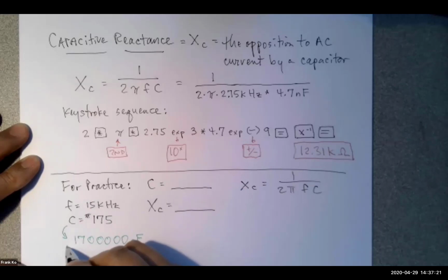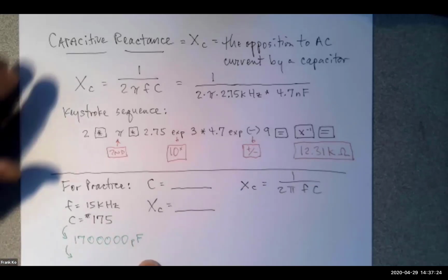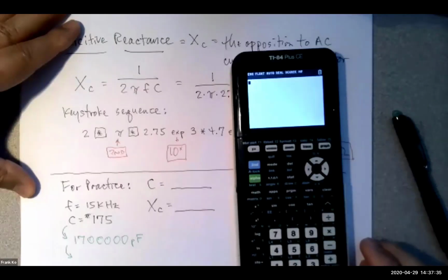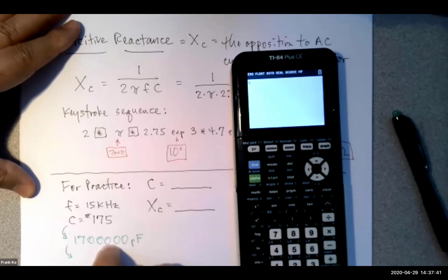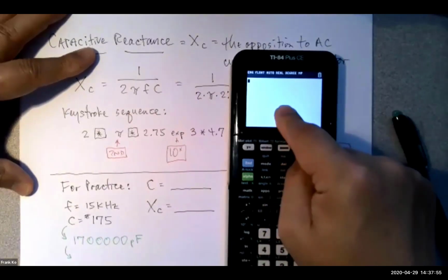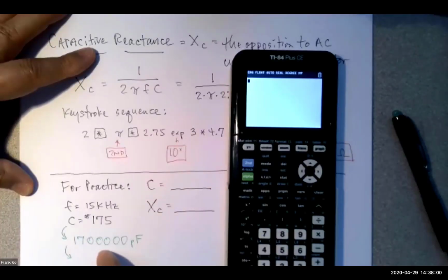What do I do with this information in the decoding process now? The question goes to Andrew. What do I do now? You want to take that over and put it into nanofarads? Well, is it always going to be in nanofarads? We need to find out. What do I need to do with this to determine what this value is going to be? Because it's not always going to be in nanofarads. You have to times it by 10 to the negative 12. Okay, and we're going to put this into our calculator, yes? Yes. So when you do that, what is your calculated value for capacitance?